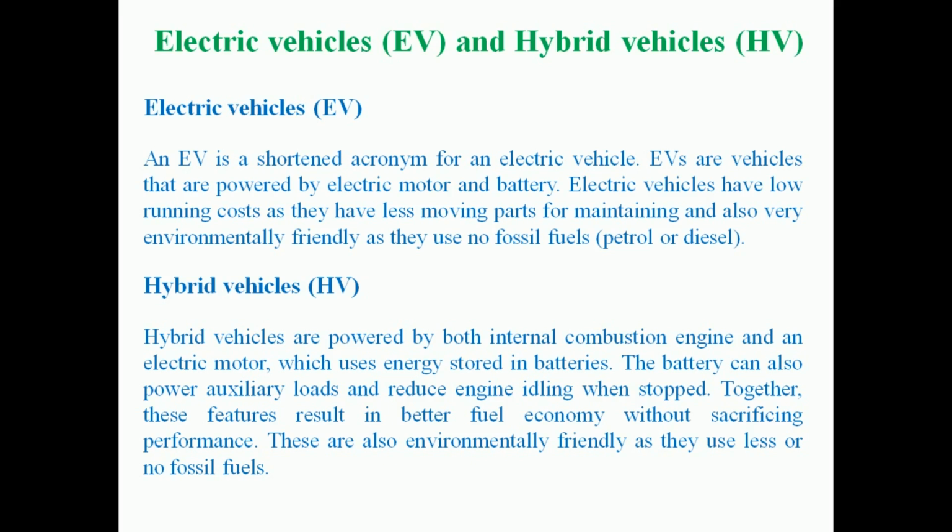Whenever the internal combustion engine is stopped, then for idling also we supply the power from the batteries only. That will reduce the loading, and using the internal combustion engine and the battery power or electric power together gives better fuel economy, without sacrificing any performance of the engine. And as we use less fossil fuel to run the vehicle, the emissions are also less.